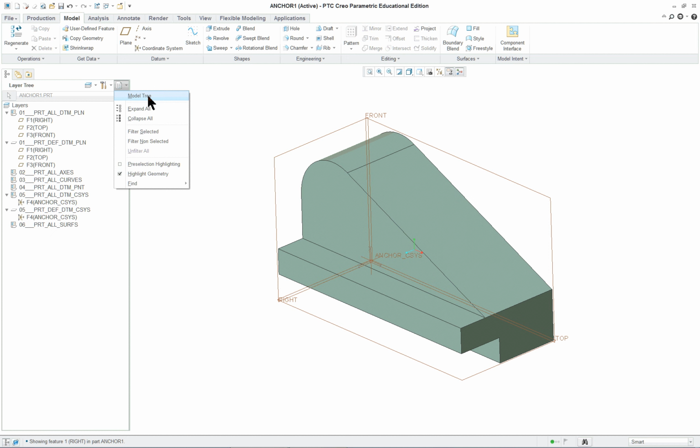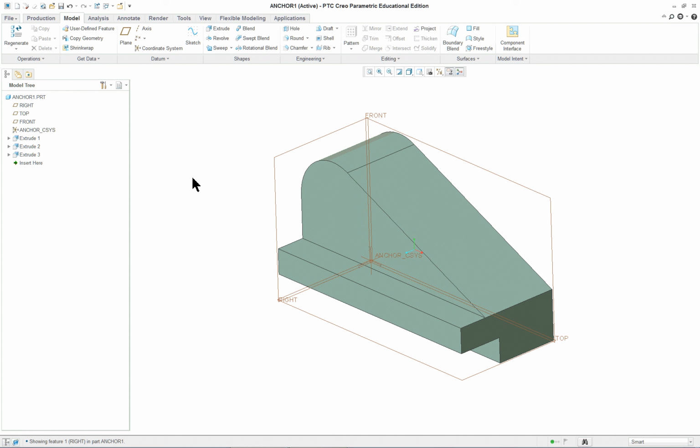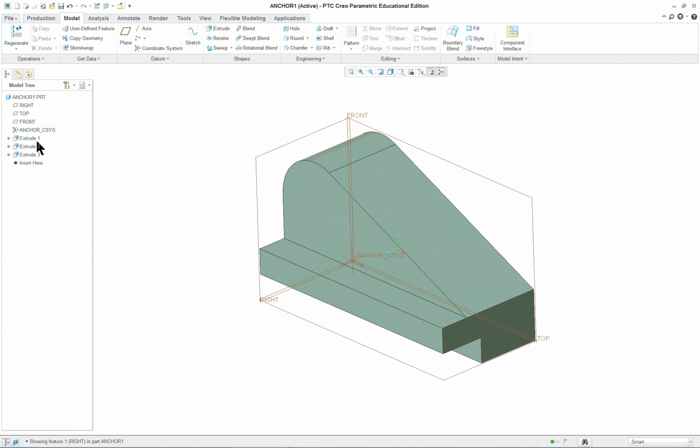So these have been created automatically, and certain items have been put on them for you to divide your information. Layers are not the same in Creo as they are for NX or SolidWorks or AutoCAD. So don't think of them that way. They're more like separations of information. Let's go back to my model tree. So we've got our first few features on there, 3 of them.